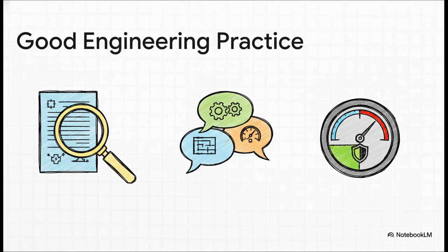So what does good engineering practice actually look like? Well, it really boils down to two things: diligence and crystal clear communication. You have to always double-check the documentation. You've got to be super specific when you talk about pressure. Are you talking design, operating, or test? And this is critical. You never ever run a system above its maximum allowable operating pressure, or MAOP, which is set specifically to keep those safety margins intact.